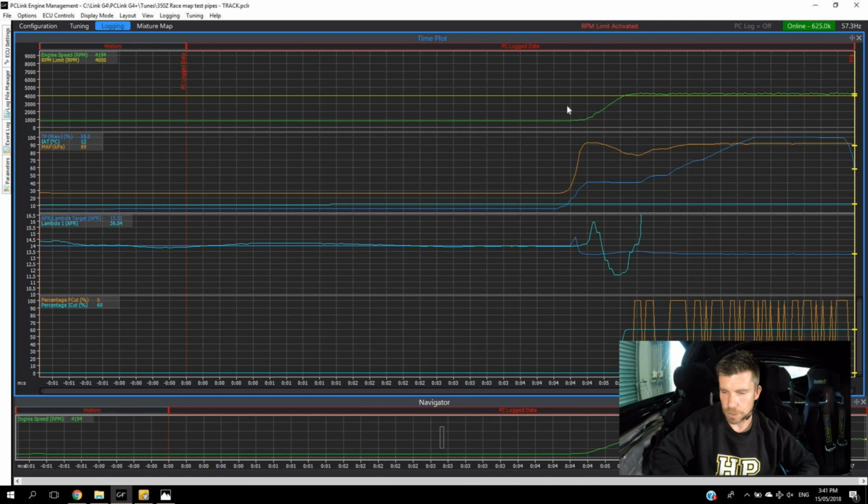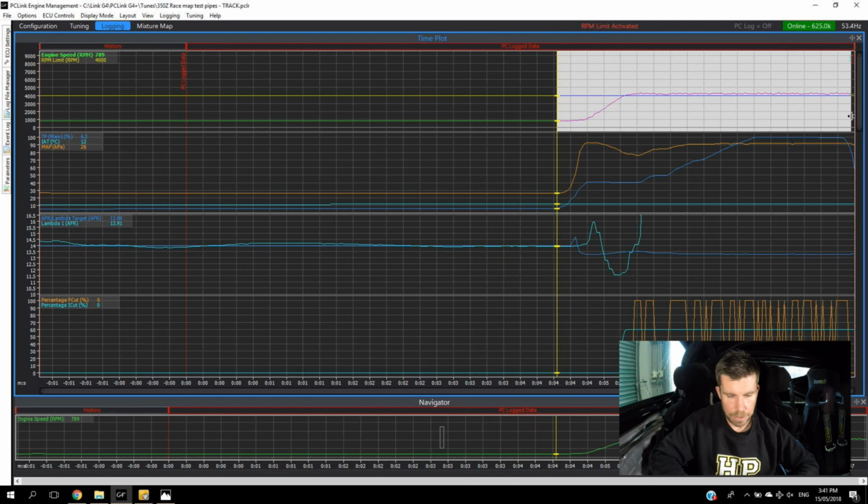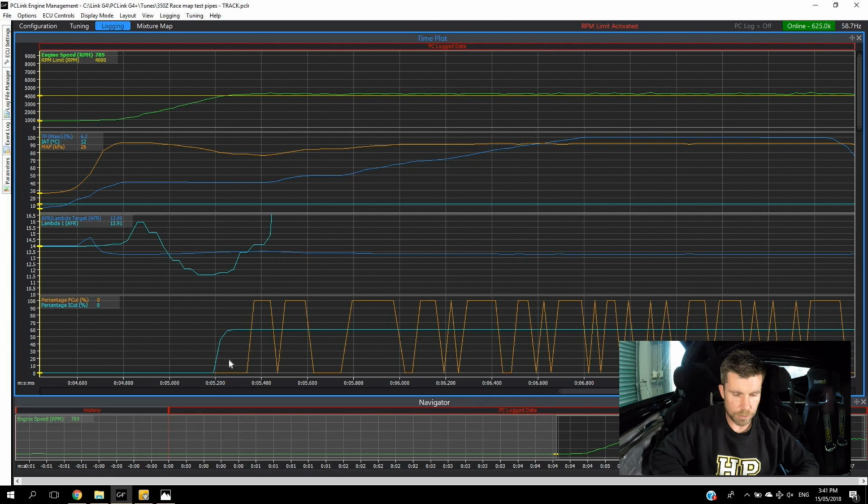Alright, let's just zoom in on a little bit of that detail there. Alright, so just as before, we've got our ignition cut maxing out at 60%, as I've said in there. This time though, we can now see that once we get past our rev limit control range plus our hard limit activation range, in this case we're at 4300 RPM, we can see that 100% fuel cut is being brought in, and we can see the spiky nature of that as that fuel cut is brought in and out and the RPM jumps up and down.